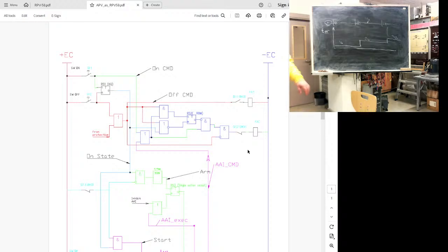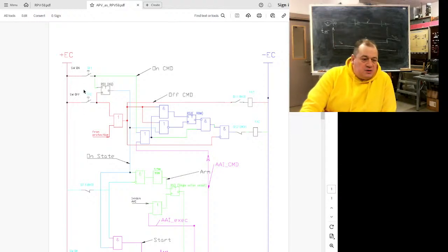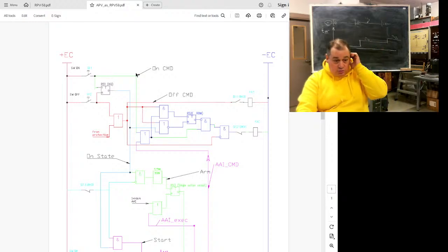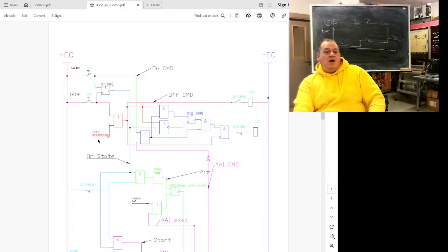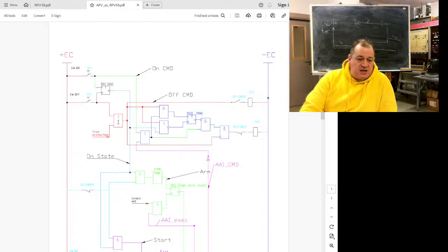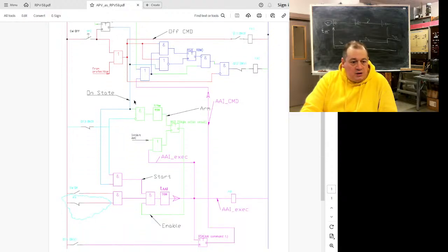So, what have I got here? I show it as a control button. Actually, it may be output from the dispatch system. Go on or go off. Off signal, or signal from protection, anyway, goes as an off command and disconnects our circuit breaker. Trigger, this one is a memory of the last command. It was on or off. If the last command was on, here will remain 1. Should be on state.